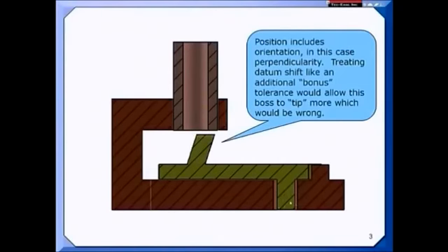You know, back when I located features with plus-minus tolerance dimensions, I would spend a tremendous amount of time trying to decide how to place the dimensions to minimize tolerance accumulation. Then others would review the drawing and argue that the dimensions should be placed differently. When basic dimensions are used, this issue goes away.